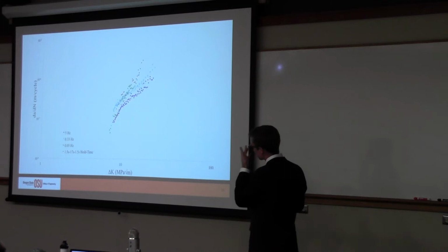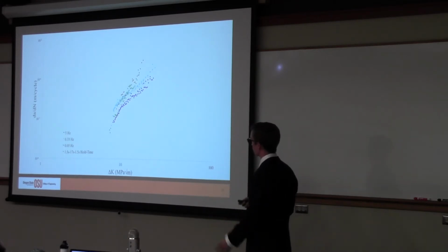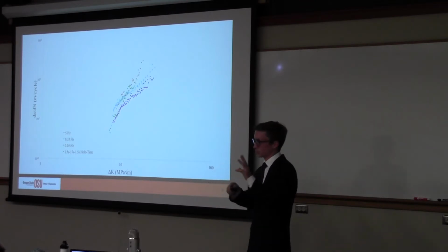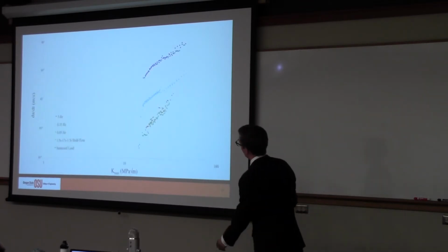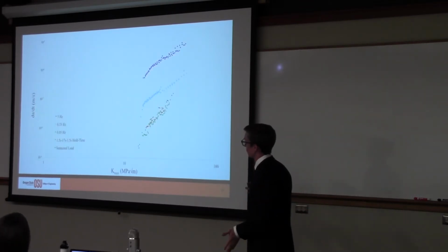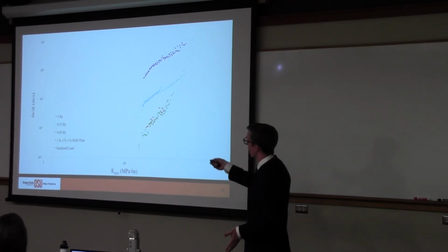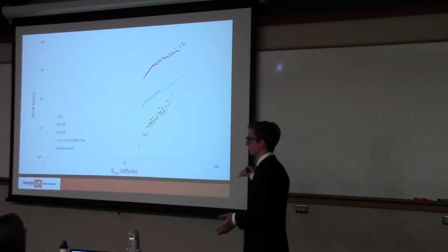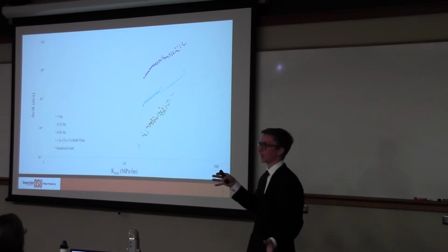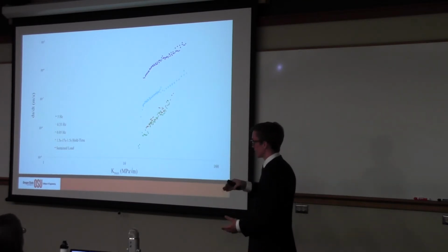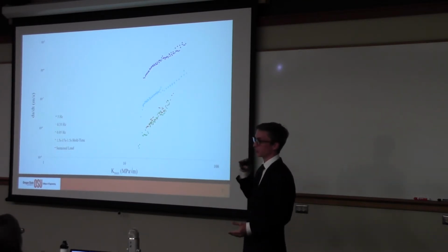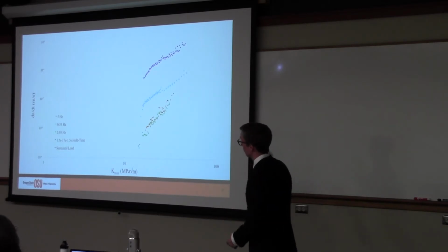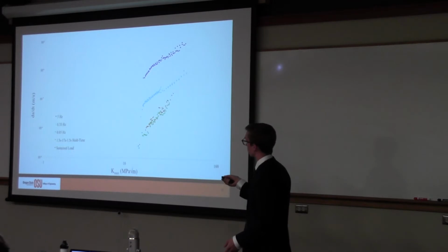I mean, if we look at this in a couple different ways, we start to get a different feel for the data. And so I'm going to show you another few graphs, and then we're going to show a bunch of samples. This graph is in the time domain. Crack growth rate per time versus K max. So we're no longer looking at delta K, K max minus K min. We're looking at just the K max applied to the sample in that loading waveform. dA/dt is the crack growth rate per time.